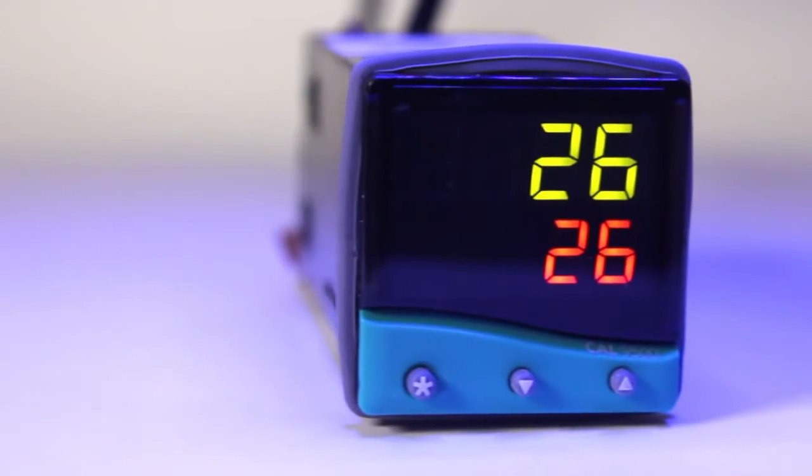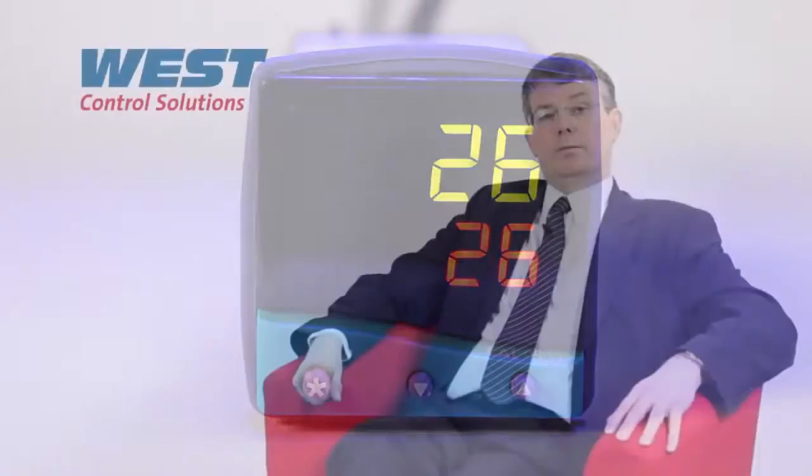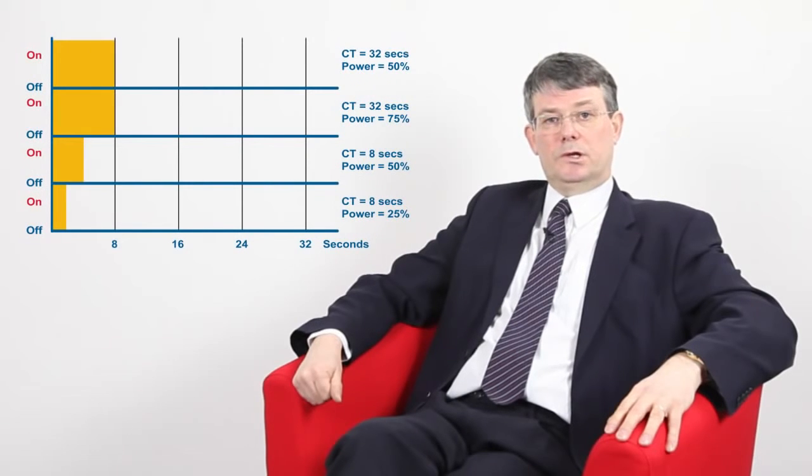There are some processes where it is not appropriate to use proportional control. For example, if you have a refrigerator and you are switching the compressor, you would have to use on-off control. A compressor cannot be turned on and off frequently, as would happen with proportional control. Even if the cycle time was set long, it would still switch more often than would be desired.